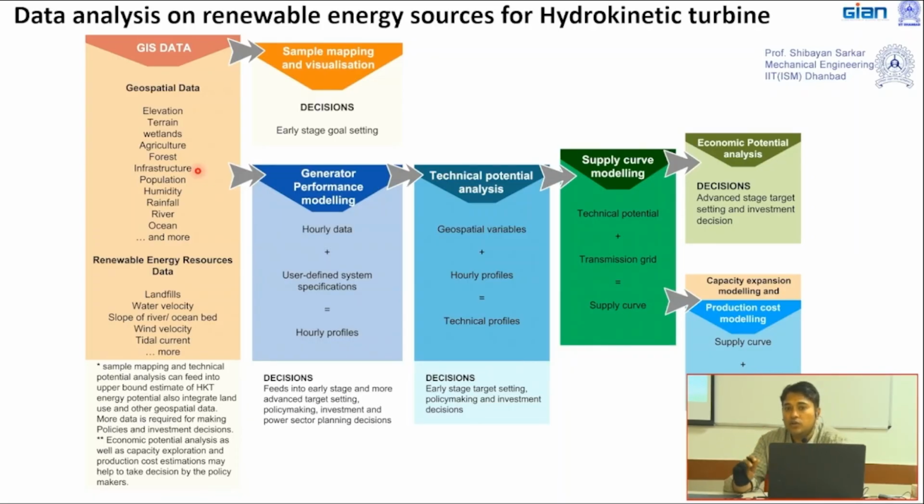Our main aim will be to find out the minimum available discharge in a particular area, in a particular channel, as well as another exercise for extreme events, that means flood forecasting. That is the maximum extent of the data, required corresponding to the failure of the structure which you are going to prepare. One is corresponding to the running of your turbine throughout the year. Another is the extreme point when your project is going to fail because of extreme data. So we need to know both.